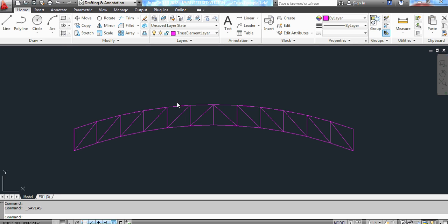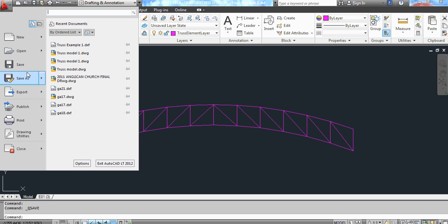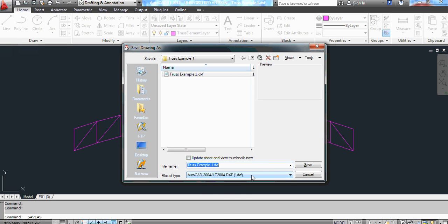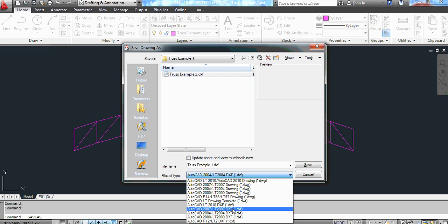After saving your work in DXF, I also forgot to mention that before you go over to Quick Structure 7, also remember to save your work as DWG. It's already saved as a DXF, so I can just click Save As and keep a copy in case you need to make reference back to your work.